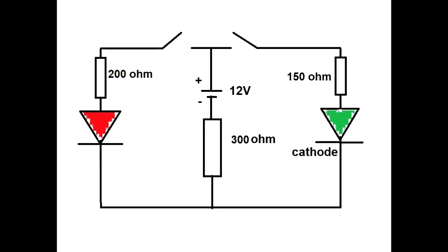Now I'm going to show you the wiring diagram for the landing gear. The goal is to have a green light when the landing gear is extended and red when it's retracted. So I used some bicolor LEDs, red and green, with 3 legs and common cathode. But in fact this is 2 LEDs in one component.